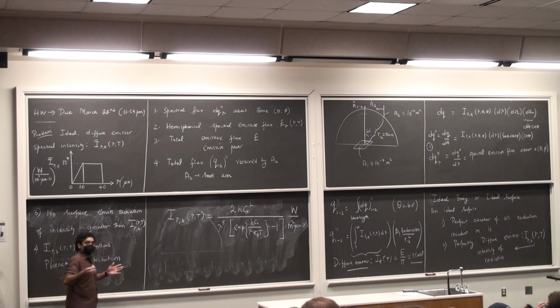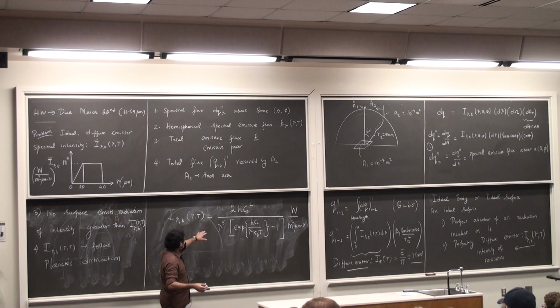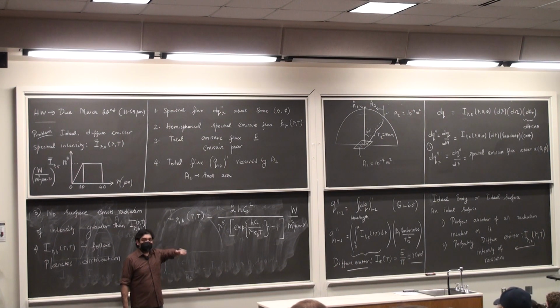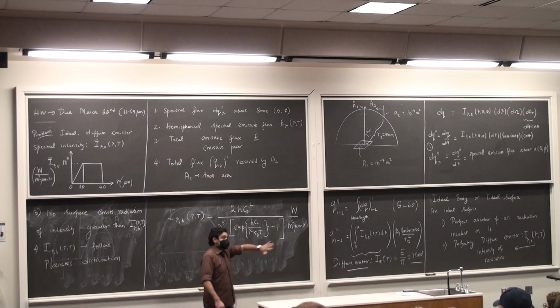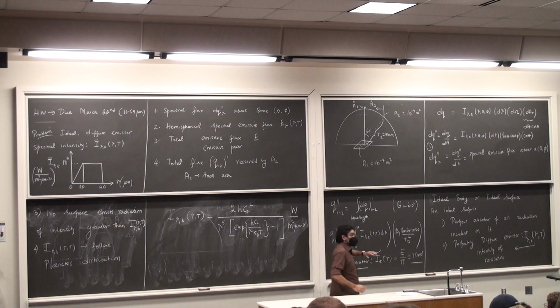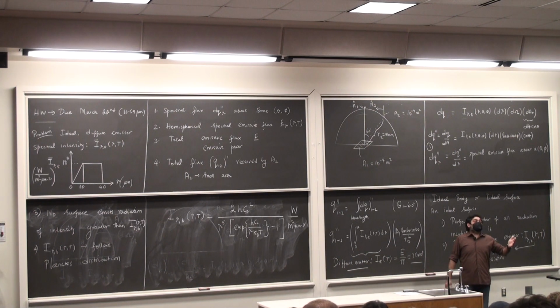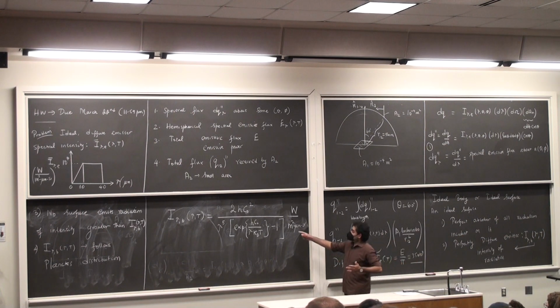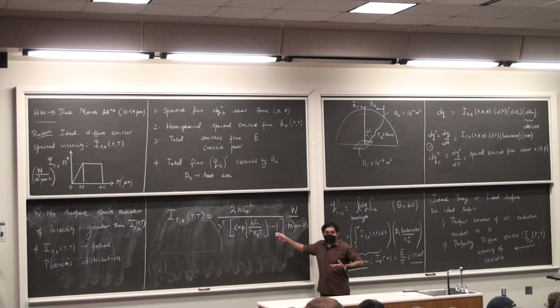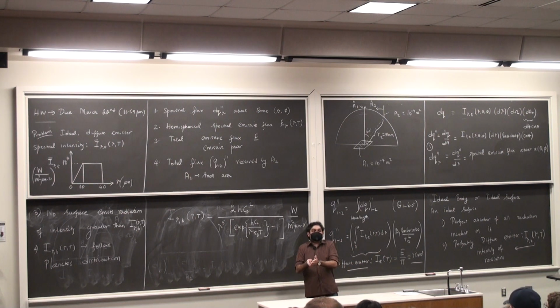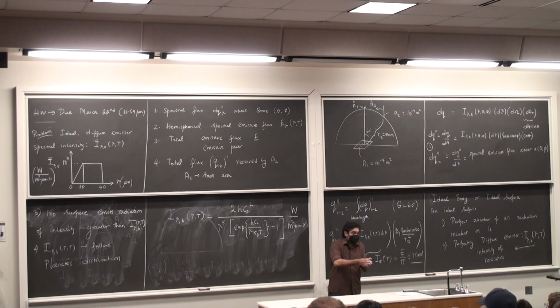So if I have an ideal surface, if I want to calculate my I lambda comma E, just calculate it using this formula. If I'm given a wavelength, if I'm given a temperature, just plug and check based on Max Planck's distribution. If I want it for a real surface, what do I do? I say that, okay, hey, I do have it for an ideal surface. The real surface is going to be at a fraction of what the ideal surface does. That fraction can be obtained from experiments.